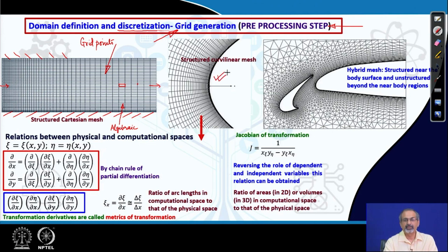this may be like the leading edge of an airfoil, and you are trying to wrap a mesh around the airfoil, and you are just looking at part of that mesh which is close to the leading edge of the airfoil. Here you can very well understand that you cannot have the same kind of mesh that you had over here. There, if you had fitted the xy coordinates, then basically the lines that you drew were either parallel to the x axis or parallel to the y axis, and then the grids were basically non-uniform.